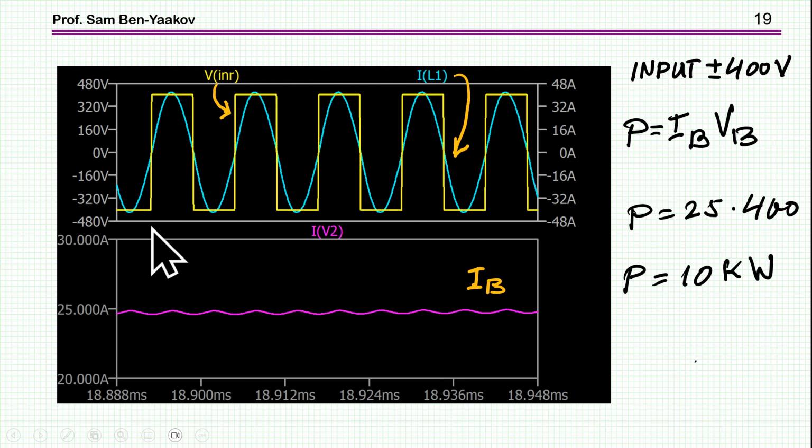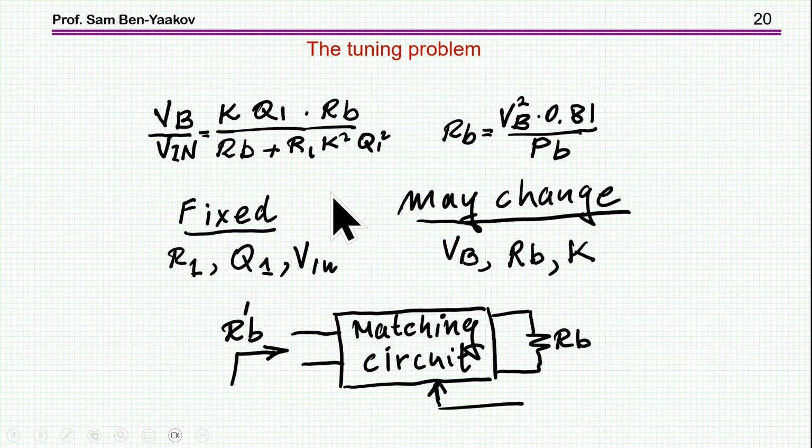What is very important is the current of the antenna at the primary is in phase with this square wave, meaning that we really don't have any reactive power, except for the higher harmonics of the square wave, which are really not involved in the losses because the current is sinusoidal, okay? The parasitic resistances see a sinusoidal waveform. So this is an excellent situation, and this actually verifies the equation of the transfer ratio between the input and output voltage. And now comes the question.